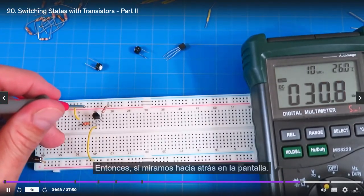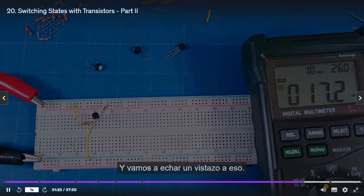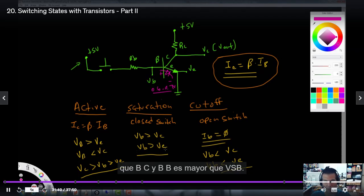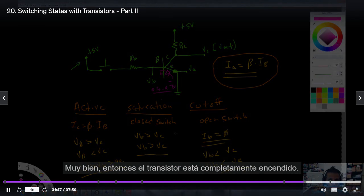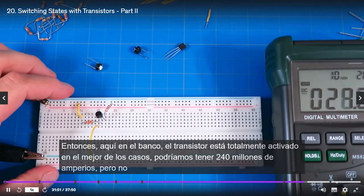So if we look back on the screen, right, and let's take a quick look at that. So back here on our screen, on our drawing program, where are we? Saturated mode. V sub B is greater than V sub C, and V sub B is greater than V sub E. Good. All right, so we must be saturated. So we're in the saturated part of that curve. All right, so the transistor is fully on. Okay, so back here on the bench, the transistor is totally on.